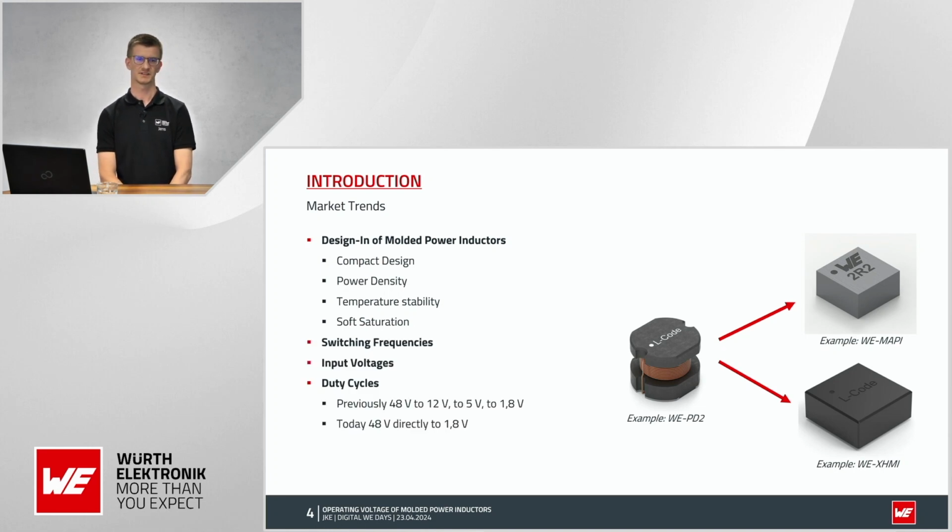Then another trend that we are seeing is a switch to higher switching frequencies. This is coming because there are new developments in FET and also in HEMT technologies. And we are also seeing that lower inductance values are required for these new FET and HEMTs. And also the power inductors can be much more compact.